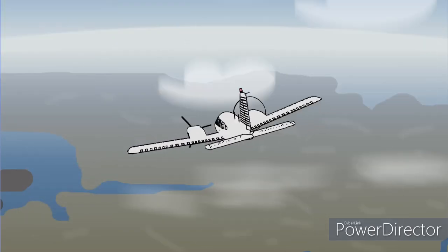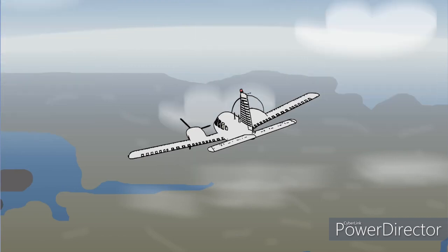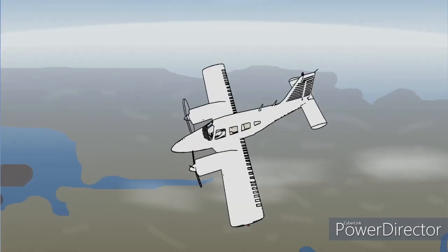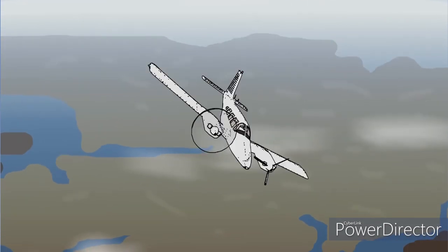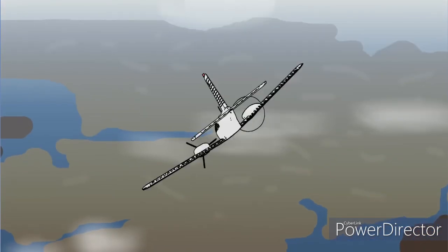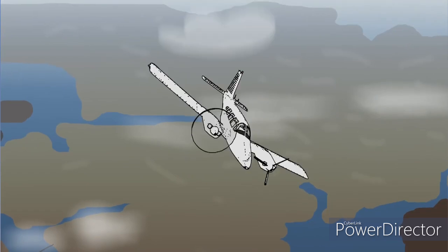This uncontrollable yaw, in this case to the left, will cause the aircraft to roll uncontrollably, also to the left, owing to the greater lift on the starboard wing whilst yawing left. The aircraft will enter a spiral dive to the left, which at the low speed would be impossible to stop with flight controls alone.